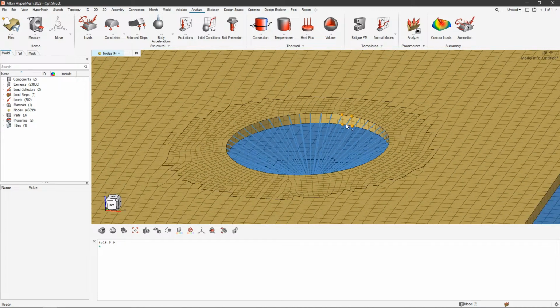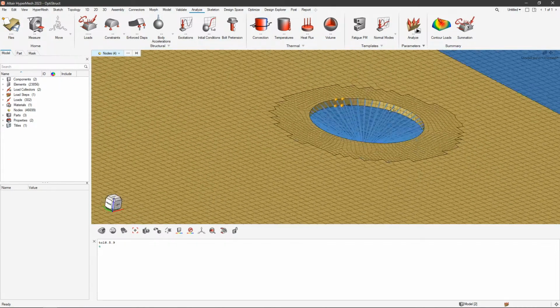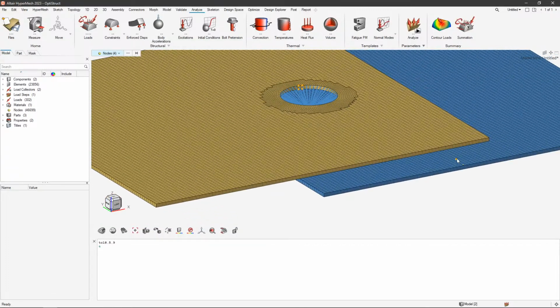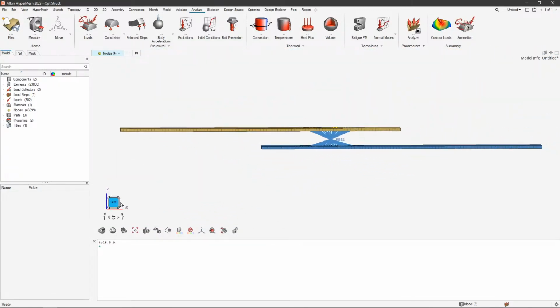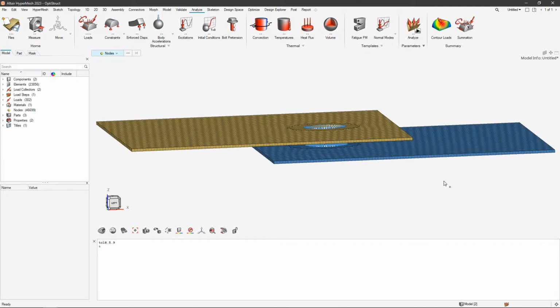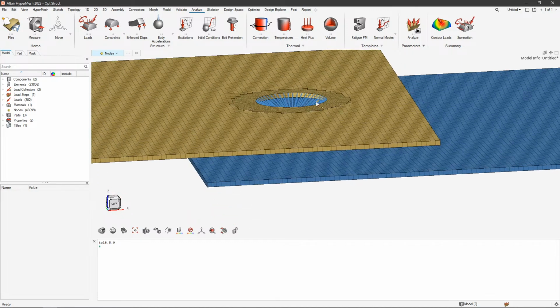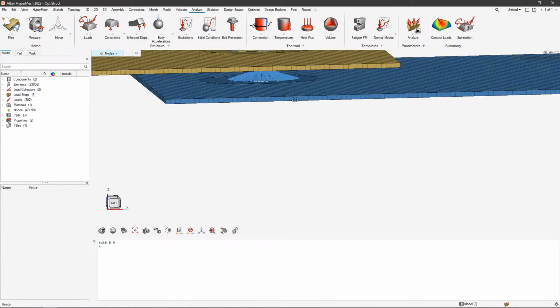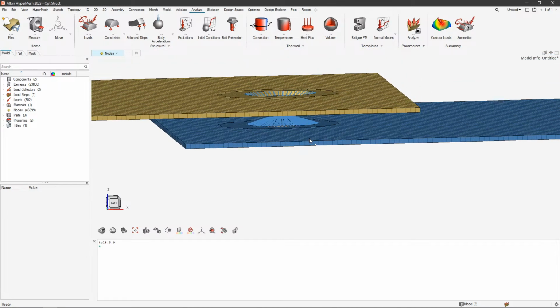Then I think the breakthrough idea was to just make the connected groups in the whole graph. So you're just doing this dissection into different parts from the whole graph. So you have a yellow part and then you have a blue part, right? With all the nodes. And then you have to change the way you are getting the groups here. So by each RBE you're just taking the connected groups from the whole graph and make this intersection of the slave nodes and each group from the whole model.